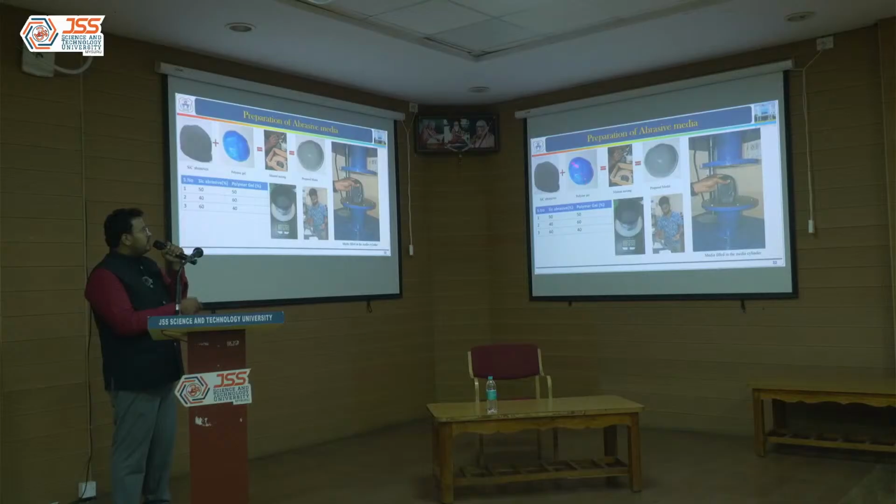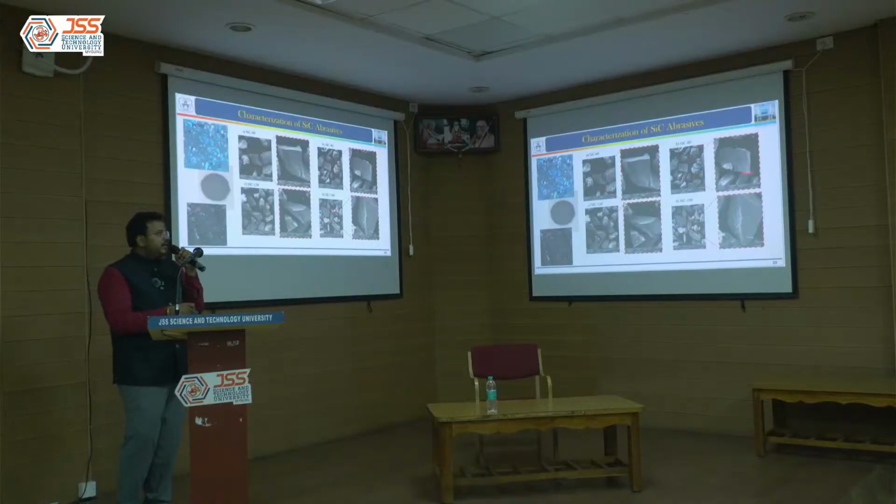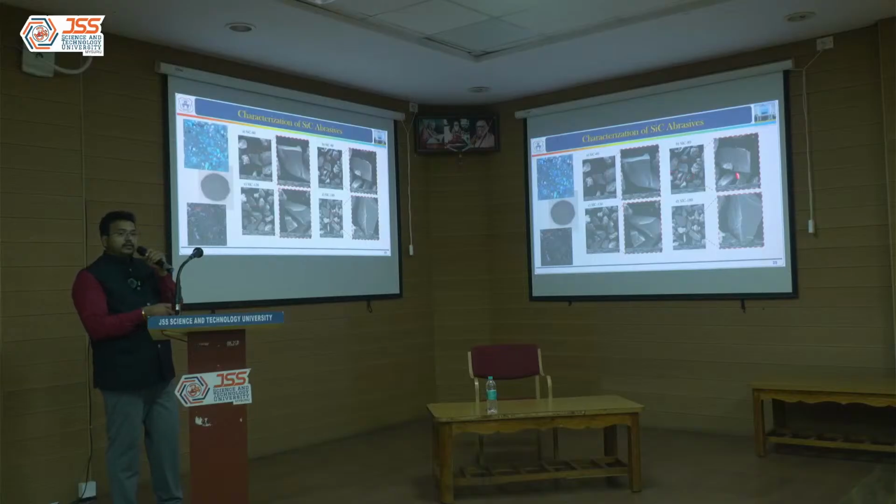The second job is that we prepared our own polymer gel and silicon carbide media. You can see the flexible tool and how it looks, and we fill the abrasive media in the machine. In our case study, we chose different abrasive particles, varying the mesh size as well as the particle size.